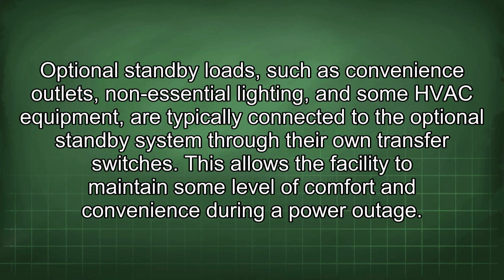Optional standby loads, such as convenience outlets, non-essential lighting, and some HVAC equipment, are typically connected to the optional standby system through their own transfer switches. This allows the facility to maintain some level of comfort and convenience during a power outage.